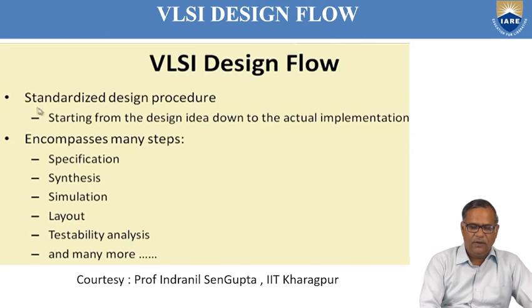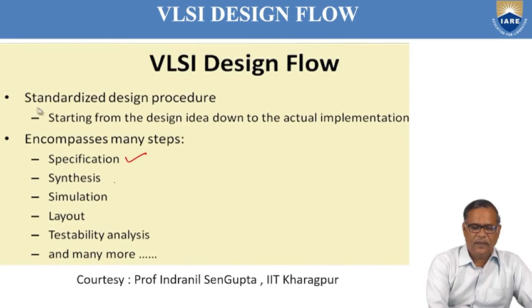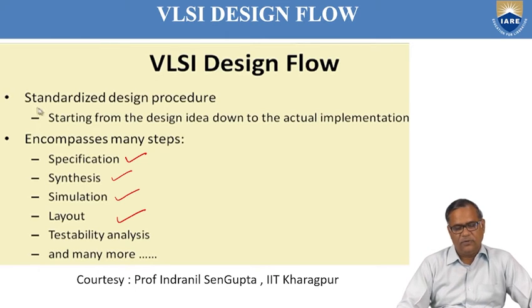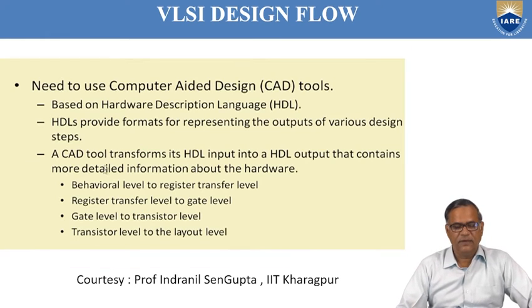You have to provide the specification, then go for synthesis, then simulation, then layout, then testability analysis, and many more. These are the steps in any VLSI design flow.